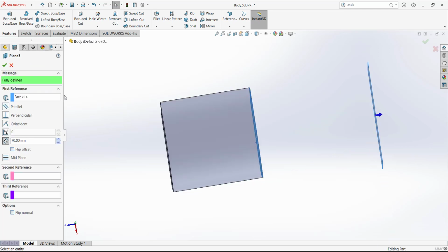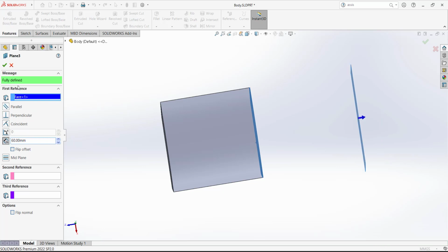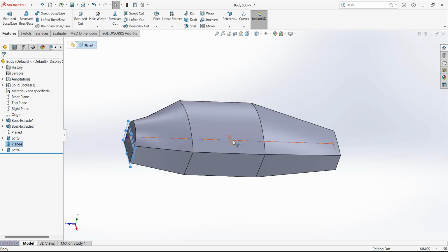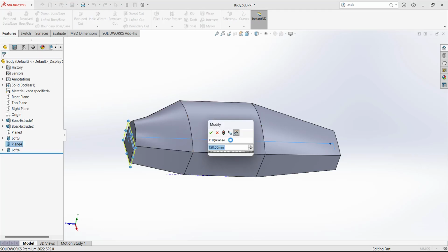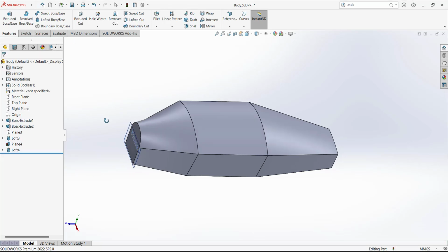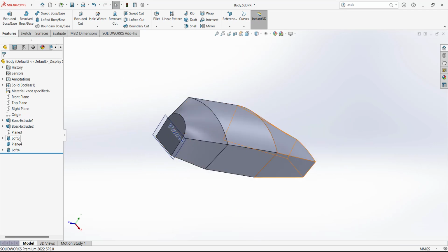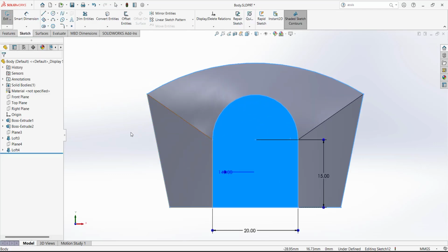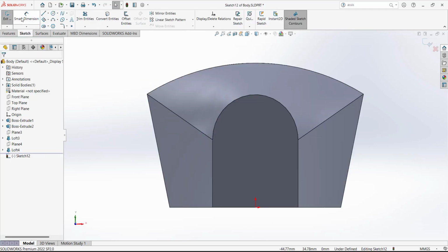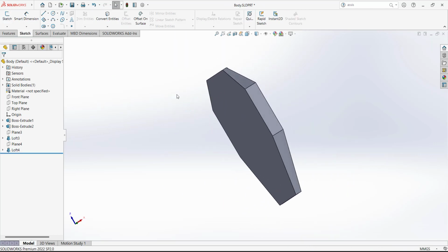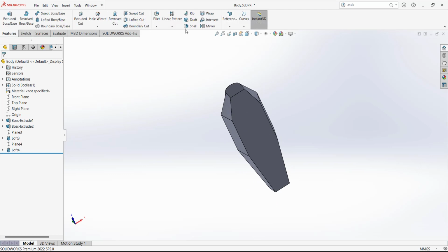Okay, and this plane 140. Okay, we are good now. So hide this, go to sketches, open the sketch on this face. Sorry, not the sketch. Now we have to make it a hollow shape. So we are going to remove the material with a defined dimension. So this thickness is 2 and select this face and check mark.